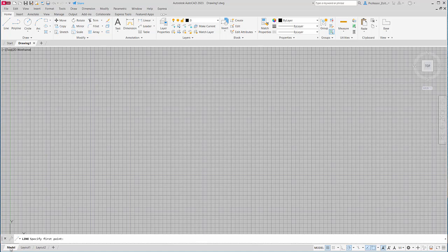Then down below that, we have different tabs. They're model space and then layout tabs. The simple way to describe this is model space is just drawing on a blank piece of paper. The layout tabs allow us to overlay a title block, and therefore we can add text, we can add other bits of information, and then we can scale our drawing within a pre-sized title block.